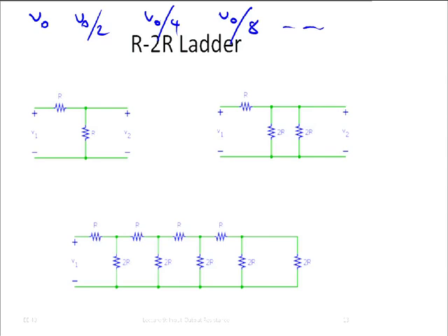How are we going to do that? Well, let's say, actually, I should have called this V1. So suppose that we have a voltage V1 and we want to divide it by 2. How are we going to do that? Yeah, a voltage divider, and we just make 2 resistors, both the same, and then this is really V1 over 2, right? No problem.